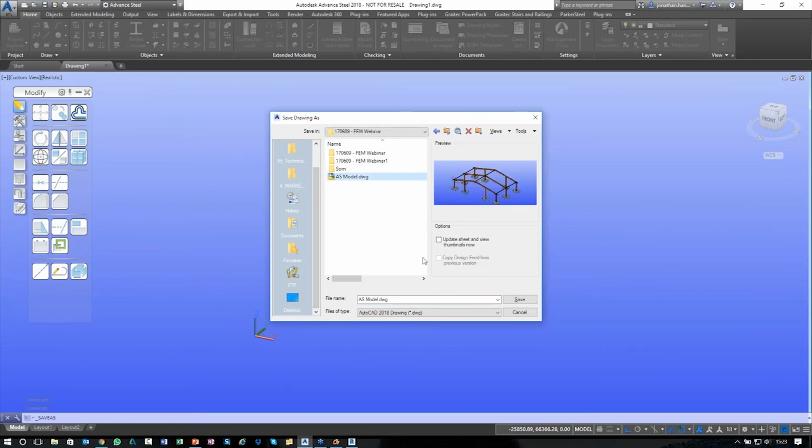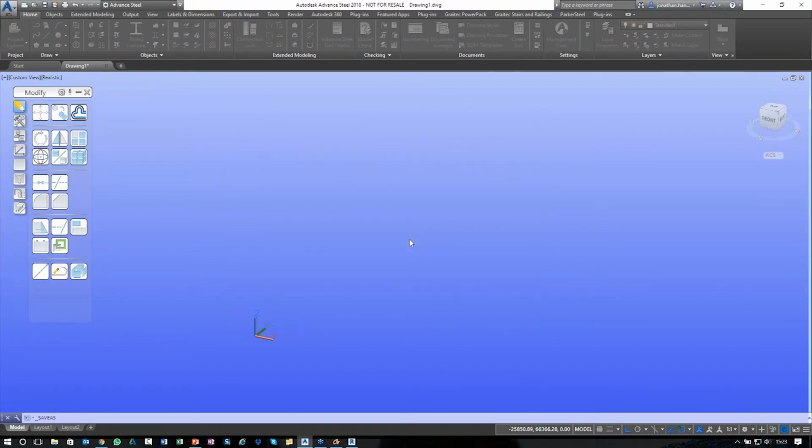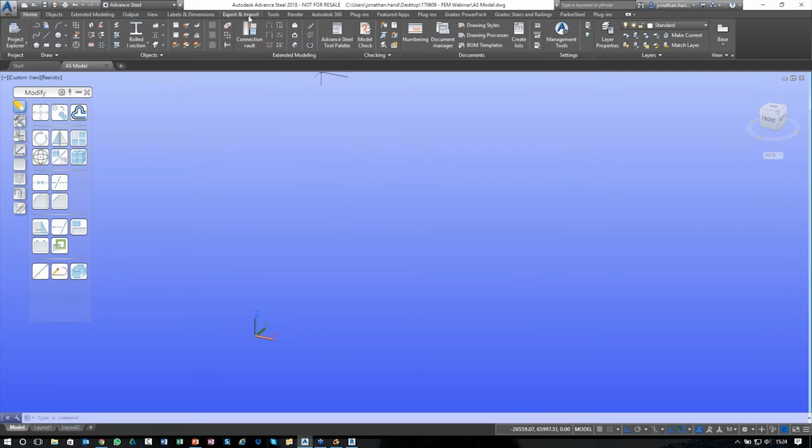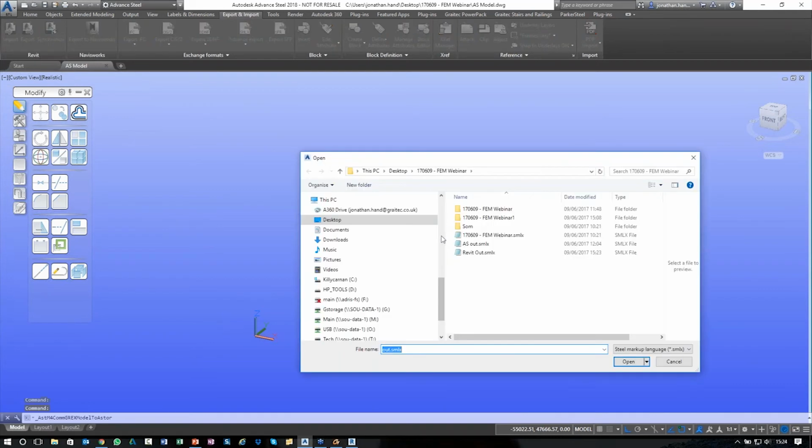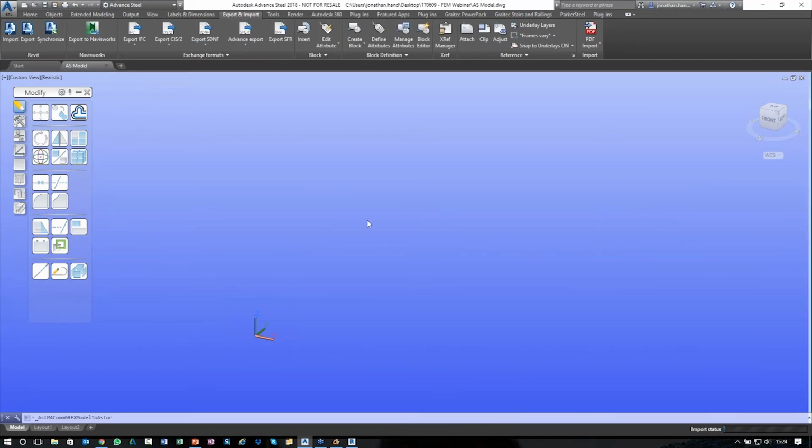So when we select it, we right click, you can see that I've got the same connection that I have in Revit here. So I can select it, modify parameters. Same connection also exists here. So we can go in, we can modify it, we can change it, we can go to bolts, bolt groups. We can say there's 3 in the second group, but they're only 75 mil.